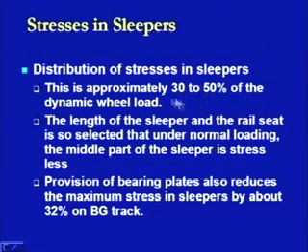This is the total distribution of stress in sleepers, and the length of the sleeper and the rail seat is so selected that under normal loading the middle part of the sleeper is stressless. This is another design factor of the sleepers.